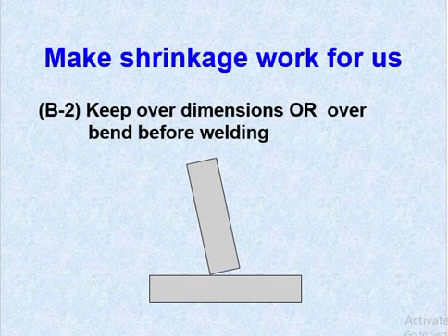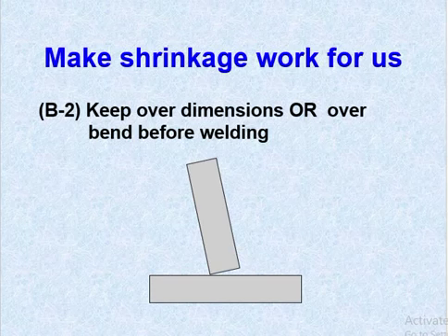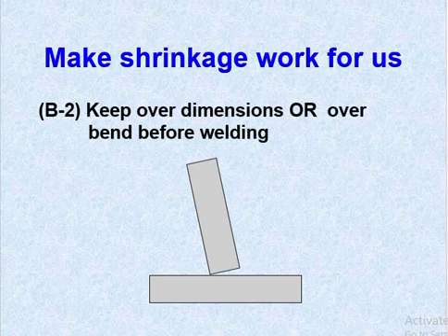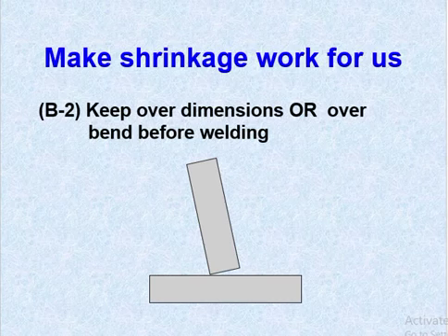So on one side the welding will be done, and on the other side you can bend a little, so after welding it will be in the same condition, but it is not the proper practice in this industry. So you have to give one support in another way, so that contraction and expansion cannot happen.